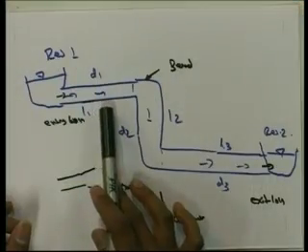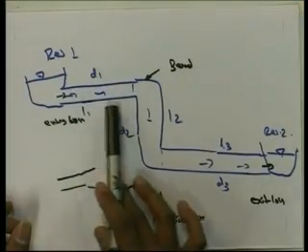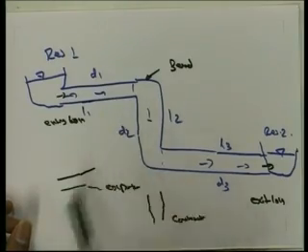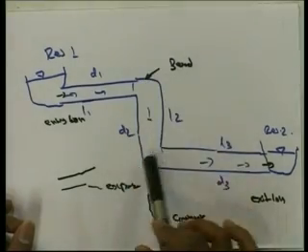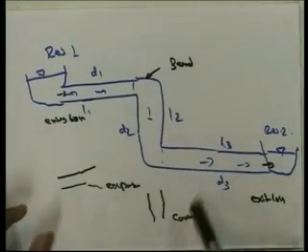With respect to this figure, generally we can classify the pipe losses as major loss and minor loss. The major losses, as we discussed, are the losses due to the shear stress or the viscous effects of the fluid and flow resistance with respect to the pipe. So, that is the major loss. Minor losses are like entry loss, exit loss, bend loss, junction losses, expansion losses, and contraction losses. Like that a number of losses will be there. These are called the minor loss.